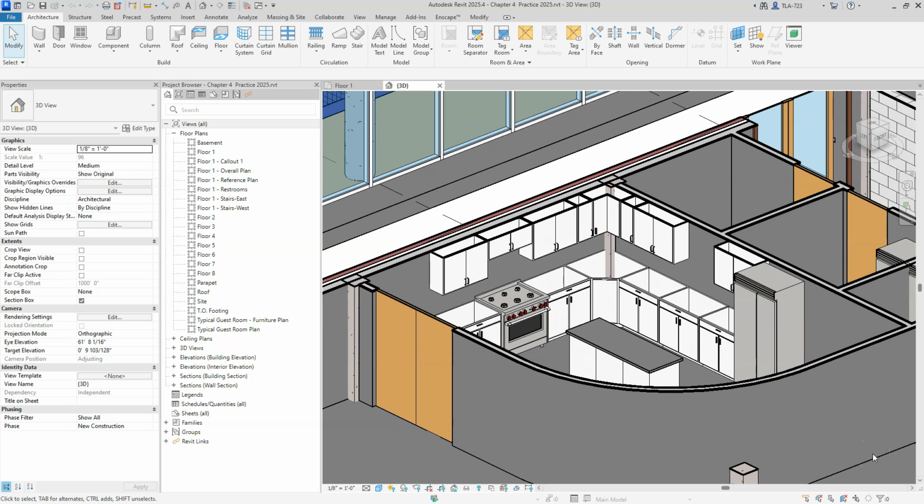One of the concepts that is related more to kitchen design in terms of how we draw it up in CAD, more so than Revit specific stuff, is that cabinets typically, if they're going to be bought from a store, are already pre-manufactured. We've talked about this in the past probably, but it's worth mentioning again that cabinets typically are going to come in 3-inch increments in terms of their width. So from side to side on a cabinet, and it's true whether it's a wall cabinet or a floor cabinet, a base cabinet, they're going to come in 3-inch increments.